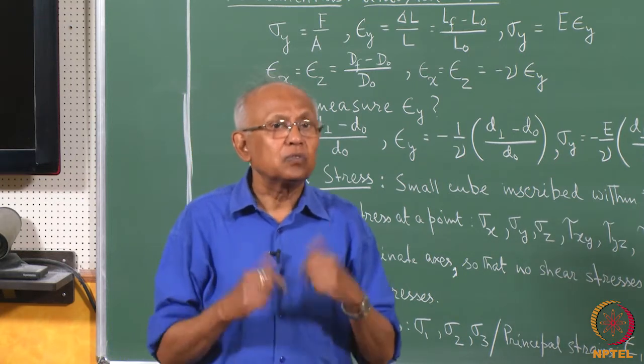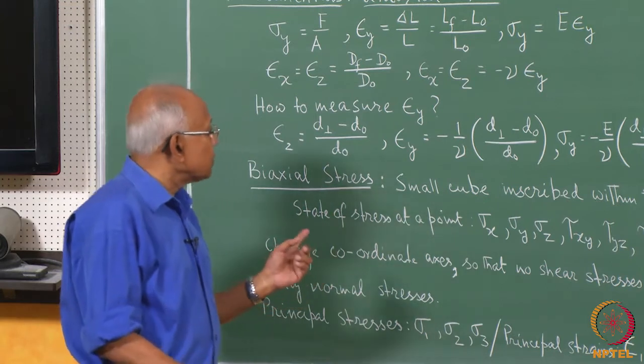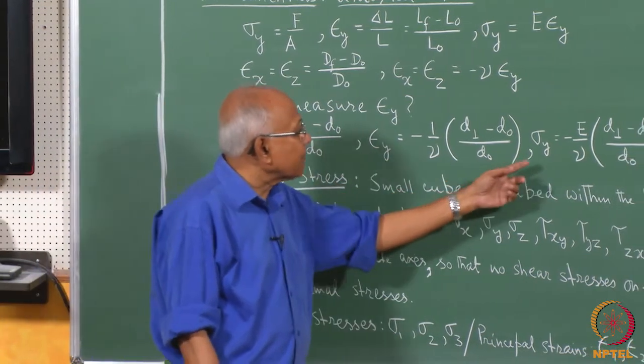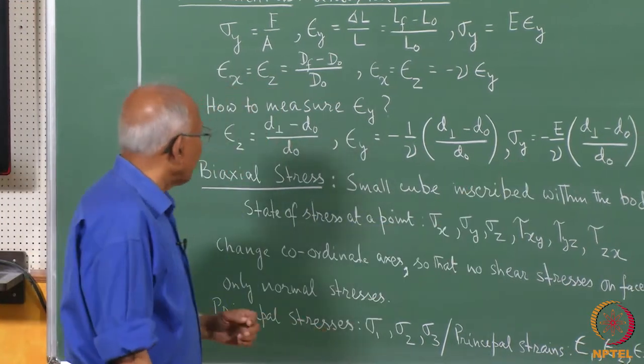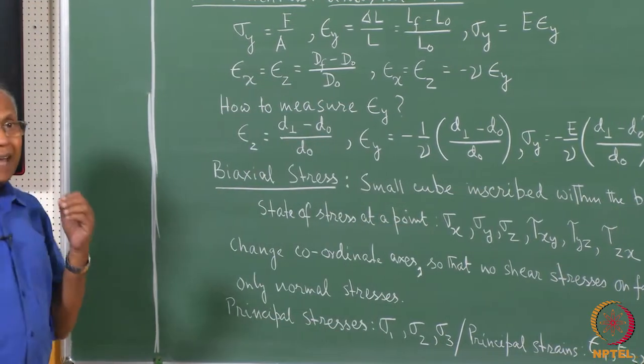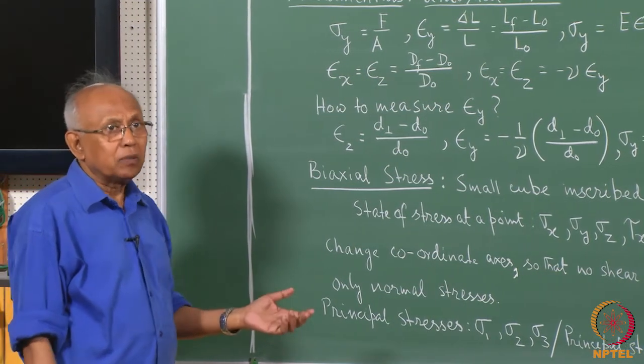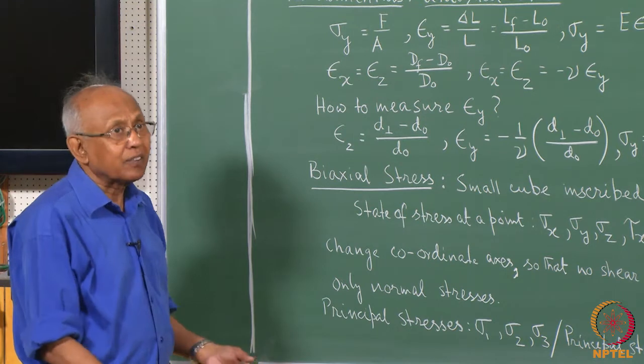Knowing these two values, it is possible to figure out the value of epsilon y, and from that you can calculate the value of sigma y. In actual material, the stress condition may be quite complex, may be a biaxial or triaxial stress system existing there.